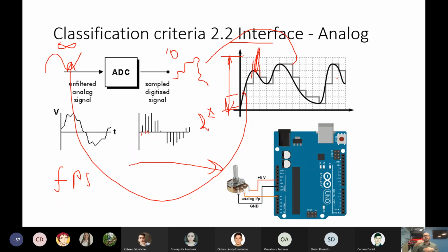It's a kind of ADC. We can have some comparators: lower or less than a certain value, after that lower or less than a second value, and so on. That means every value needs an additional piece of hardware, and for every one we'll need more, but it depends on the construction, of course. The source of the analog signal we can have on this potentiometer. So it's a variable resistor, and we will see.